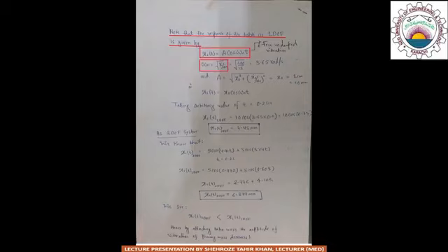Since k is the stiffness of the supporting columns and the table is supported on 4 columns, each having a stiffness of 50 Newton per meter, therefore k is equal to 200, and m is the mass of the table, which is in this case 14.96, or approximately 15 kilograms. So the natural frequency of the table or system is equal to 3.65 radian per second.